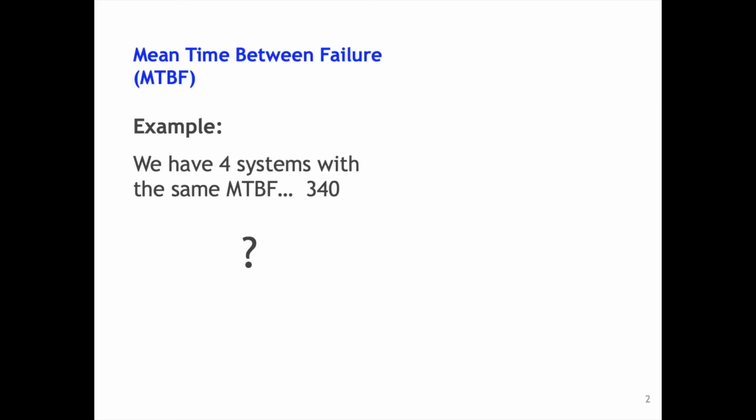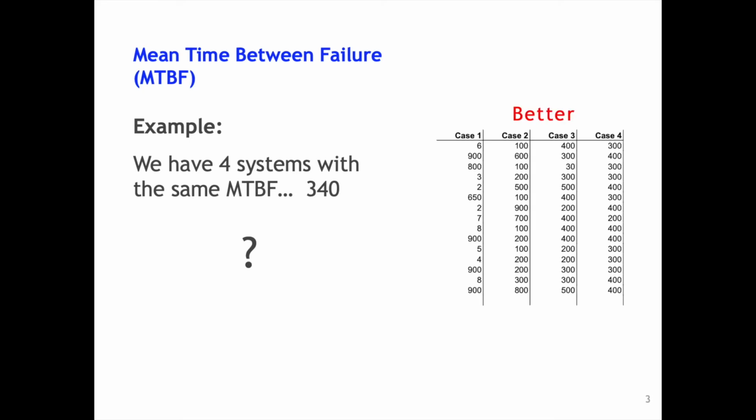Let's say we have 4 machines that have about the same average time between failures, or MTBF. We might infer that they are all operating alike. However, averages are misleading. A better approach would be to look at the actual times to each failure. Here you can start to understand a lot more. Out of the 4 pieces of equipment, case number 1 certainly looks different.